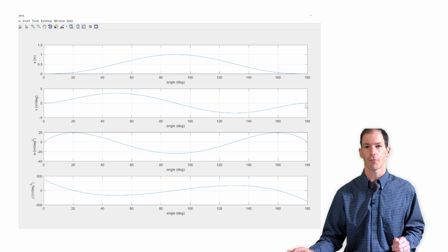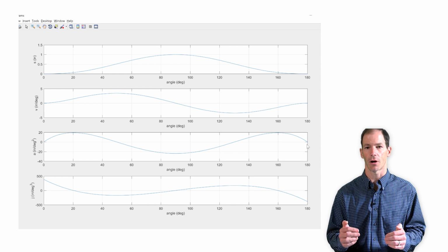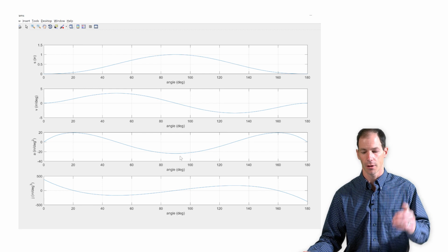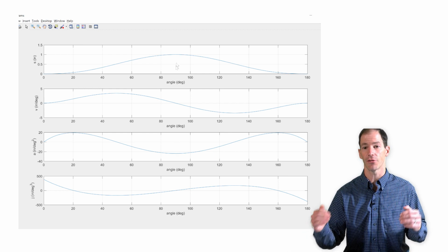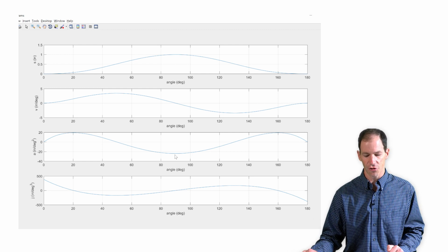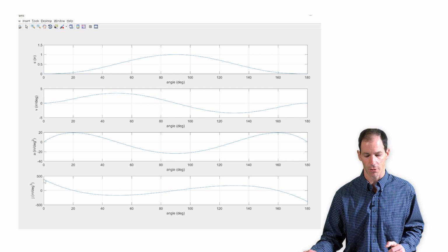You'll notice that unlike when we matched the two rise-fall double dwell segments where our acceleration went to 0 in the middle, here we still have acceleration even though we're crossing through our peak rise position. That then allows the magnitude of the other accelerations to be reduced. And then our jerk, even though we have a discontinuity here at the ends, that's still acceptable because we have continuous acceleration. We just have a step in the jerk at the two ends.